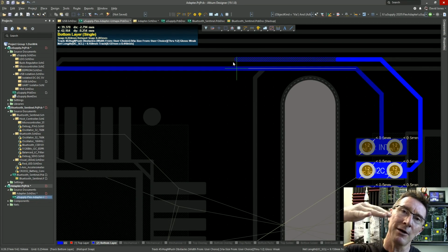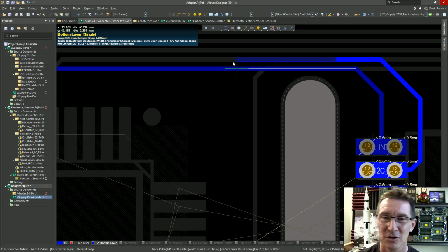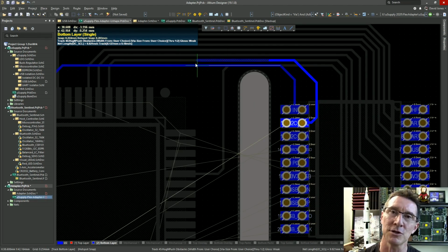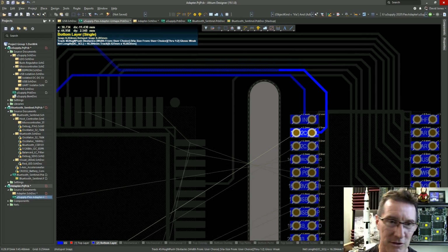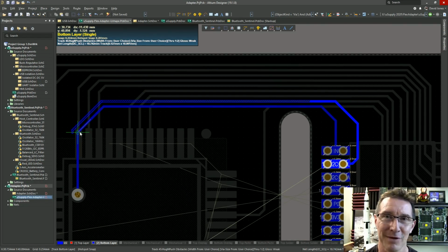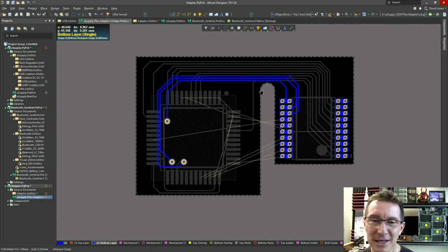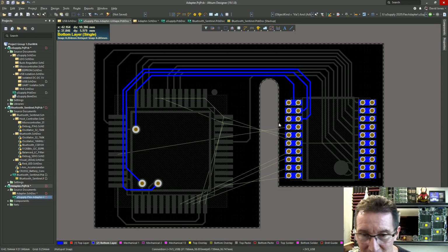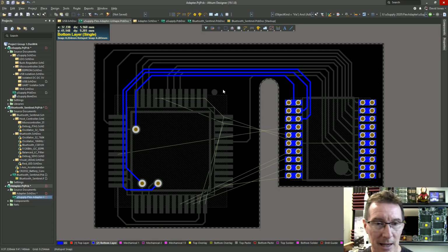You may not have one trace above the other because there can be slight mechanical things there when you really get into tight bends. So a technique which is sometimes used is to offset your traces like that, but for something like this, it doesn't matter. Actually, I've come a gutser here a little bit, because I can't obviously route them out in this direction, so I've routed these ones lowest point down here, because I might be able to snake one up there, perhaps, but it's nothing like sneaking one on the side.